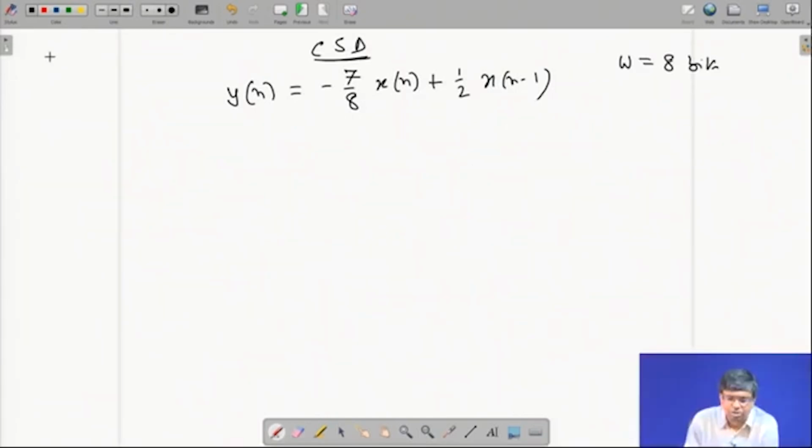But whatever we do, this job cannot be violated. This is the job: I must generate the same correct yn, maybe by the bit serial method, but it should produce the same correct yn. And then in a bit serial system, the bits of yn also should come out through a single bit line, serially. First the LSB, y0n, then y1n, y2n, y3n, up to y7n, serially. So the input will be x0n, x1n, dot dot dot x7n, in that order. The output also will be y0n, y1n, y2n, dot dot dot, in that order.